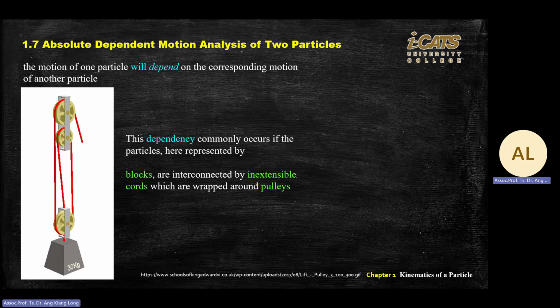Okay? So this is the common sense you need to know. Will the object move or not? If you cannot do the normal logic, the rest of the question's answer will be wrong, because you don't know the direction. So this is common logic. If you live on Earth, the much heavier object will pull, and the lighter one won't move. If it won't move, then it becomes a static question. In a static question, everything equals 0. Then you balance the system.